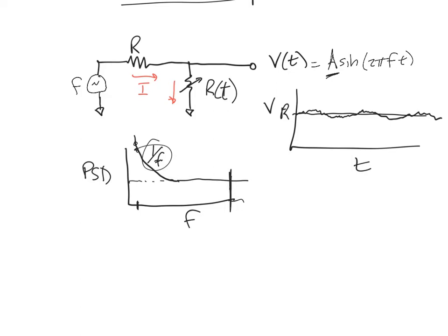But now the thing that I'm interested in is the amplitude of a sine wave out at some frequency f, out where the noise is white. So I can use this technique to move my measurement up to high frequency where the noise is white, where I'm not subject to these drifts, and life gets a lot better. The measurements get a lot more stable, a lot less 1 over f, less drifty.